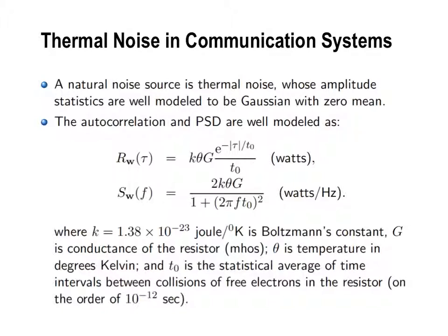They can be represented as K, the value of the noise. The power of the noise can be represented as K times the temperature. K is the Boltzmann constant, right? Times the temperature represented in Kelvin, right? Times G. And what was G?